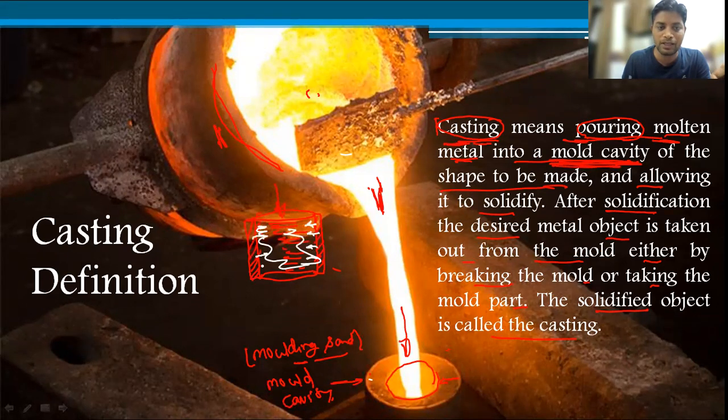First of all, the liquid is coming into contact with the solid material, and we are also using moisture in the molding sand. So the moisture evaporates, but as the liquid material comes in contact with it, it will start solidification. Solidification means it will try to move towards the semi-solid or solid state.